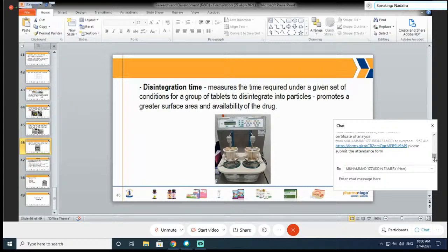For granulation using the roller compactor, basically you look at the ingredients and see their process, whether it is the same as wet granulation or not. If it looks like wet granulation, usually they will use a binder. We can get the information on the manufacturing process from the patent. Also the properties of the API, whether it can go for wet granulation. If we cannot, our first approach is direct compression. If it's not feasible, go for wet granulation. That is our practice.